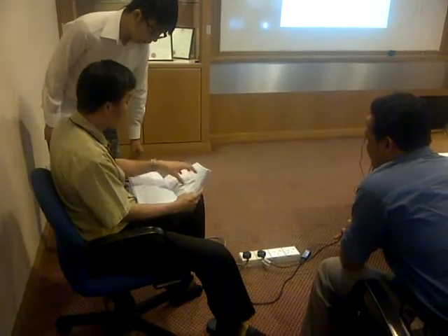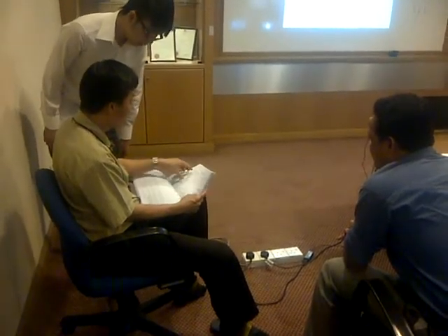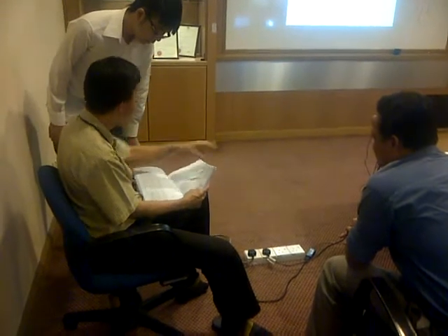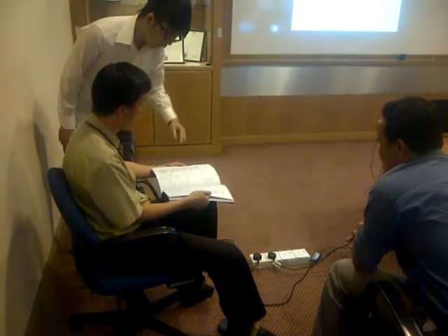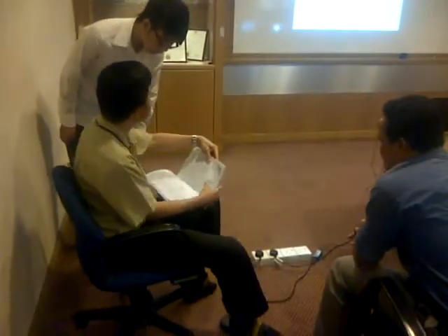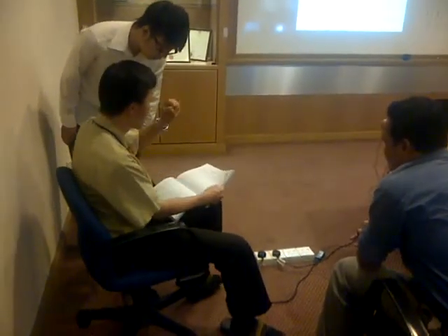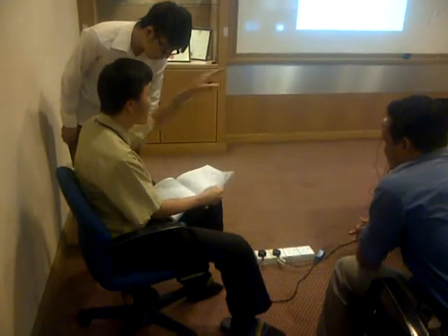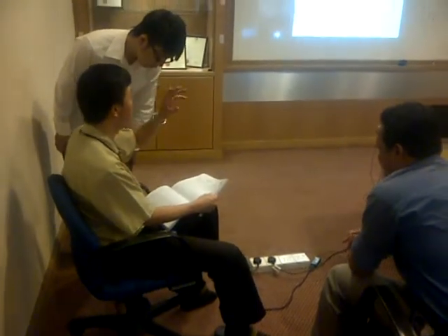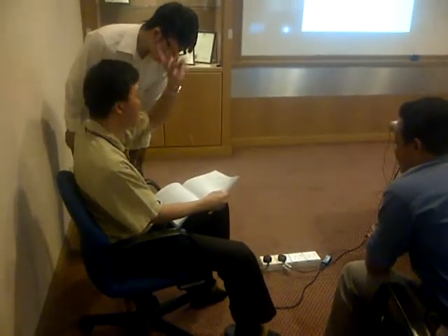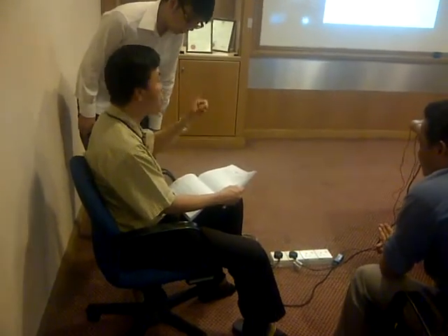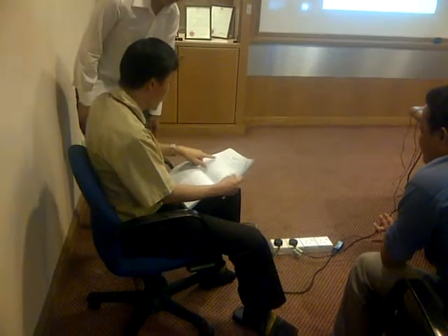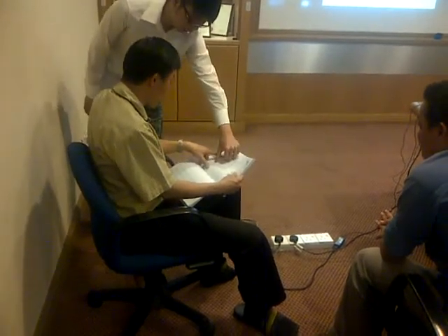Now you need to know the installation method. The installation method, you got reference method 4, 3, all these. You can refer from here. What is the installation method? Normally for this lighting circuit, normally it is in an enclosed conduit. It can be enclosed in concrete. Some certain areas above the ceiling are not enclosed in concrete. So to play safe, I will assume enclosed in concrete.